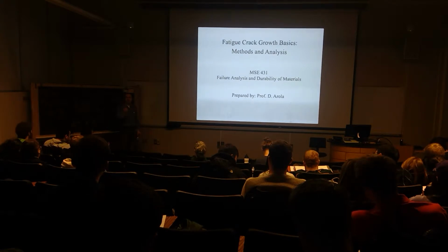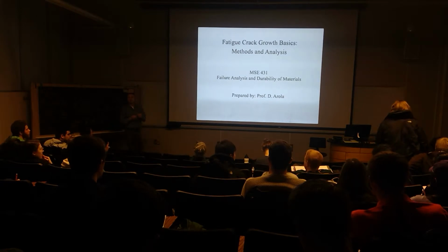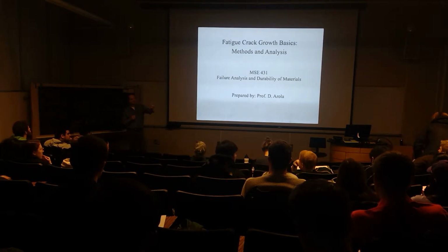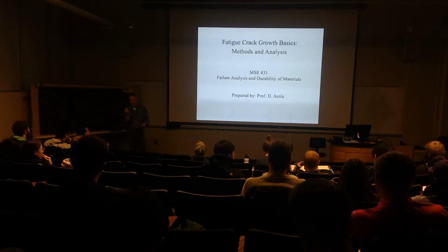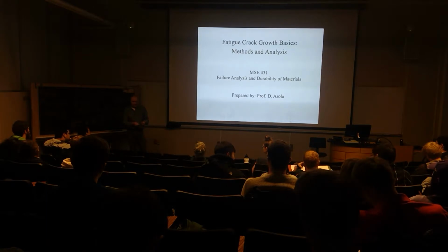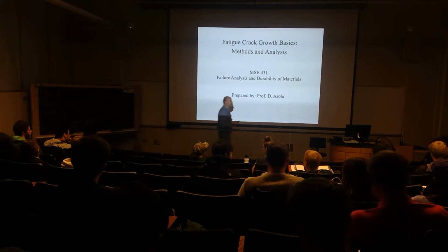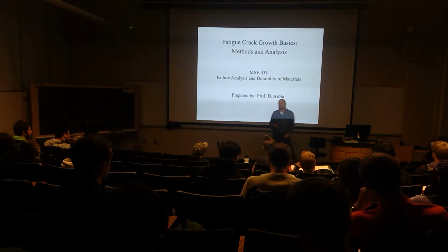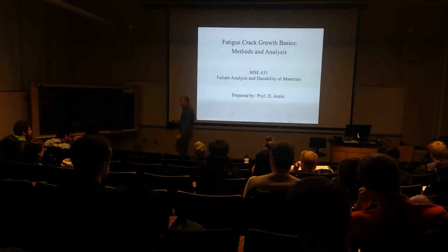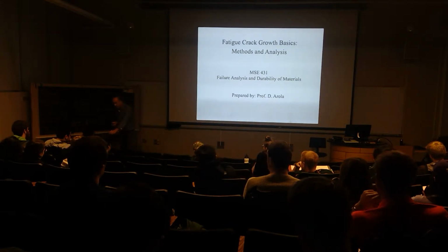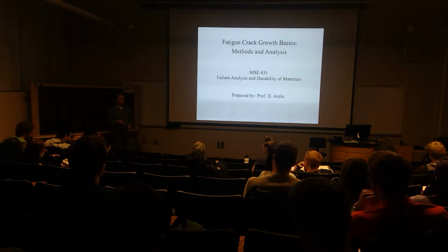So I've got another, let's say, this is like a quiz. This is a case study. So this is polycarbonate. All right. So this is a polycarbonate tensile specimen. It has not been subjected to any loading, and this is one of the specimens that actually was subjected to the point of failure. And I'm going to pass these out, and then we're going to talk about whether this was ductile or brittle. Okay. So that's that, and I'll give you the loop in case you want to see it, because actually what you can see is you can see radial lines on the fracture surface that are representative of the direction of crack growth from the point of initiation.